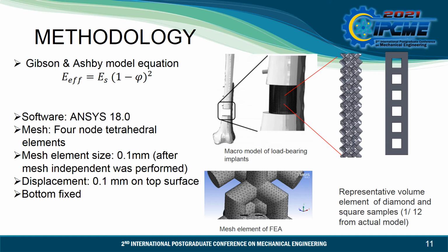Second one is the finite element analysis from the ANSYS software for the quasi-static testing. The sample has been meshed into 4-node tetrahedral elements with 0.1 mm element size, with a displacement of 0.1 mm on the top surface and fixed at the bottom.